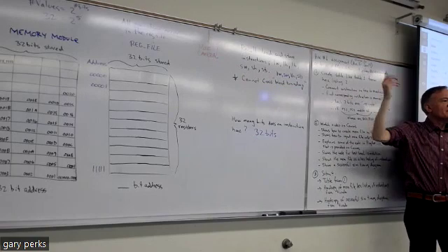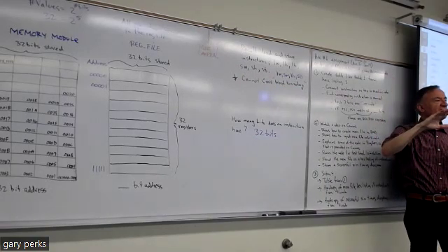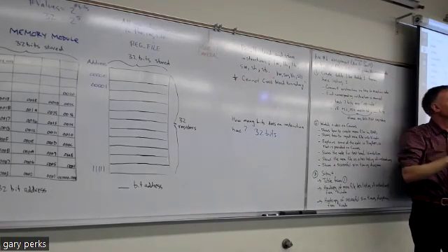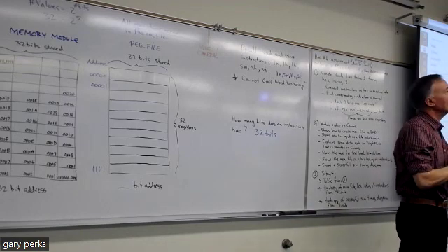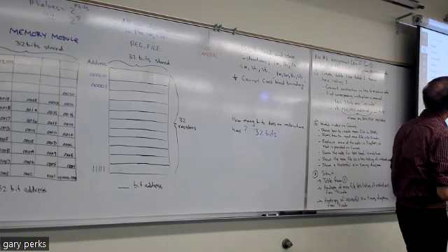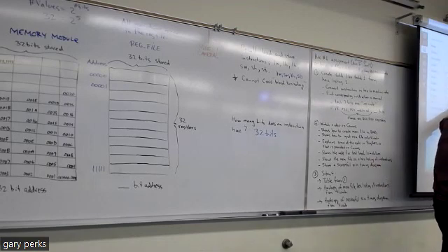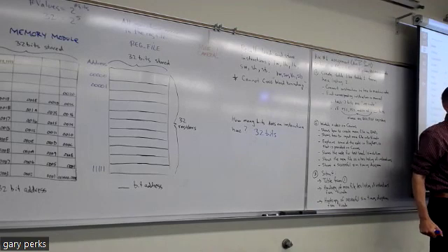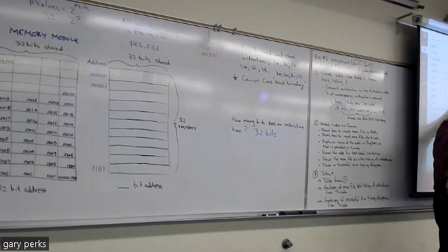So this assignment, part of it is showing you how to program the Otter, or at least how to come up with the file that you put in Vivado to program it. So one of the things I wanted to point out, first of all, is you're going to need this design source file here. This is the ProgROM SystemVerilog file. Dr. Hummel designed this, so we're not expecting you to design the program, it's already designed for you. So you would just download that into Vivado.